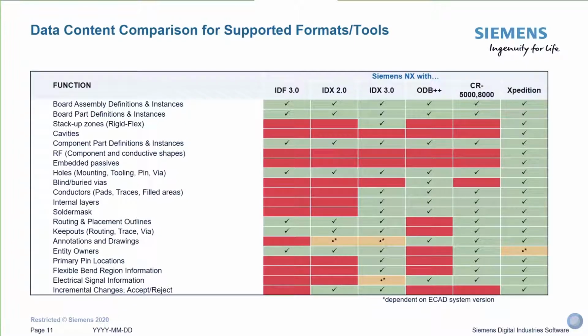Now, when it comes to importing, if we look at the next slide, there are a lot of different formats that we support via PCB Exchange. For today's presentation, I'd like to bring your attention to a couple of things. There's a lot of information in this slide, but when it comes to thermal simulation, or simulation in general, the file formats that we recommend would definitely need to have all the copper and stack up information.